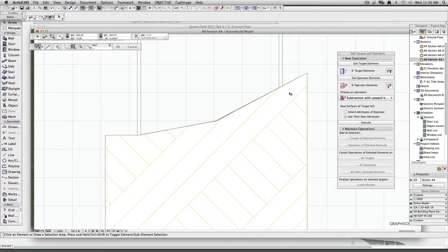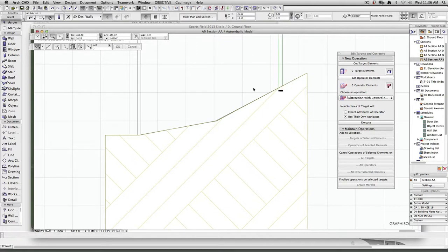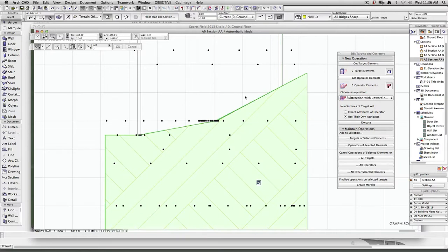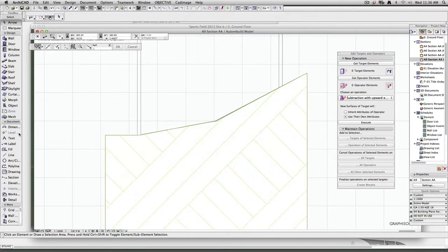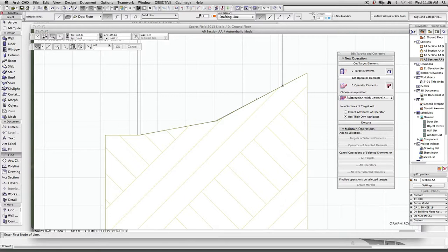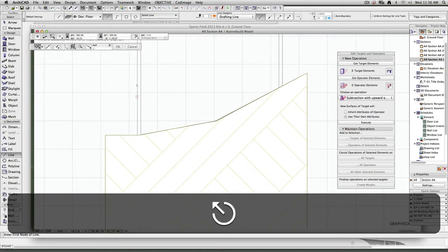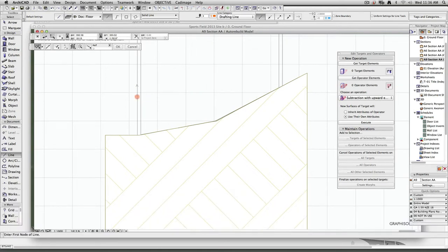So that means, as I said before, that's going up to 18.13. So let's say I make my stairs go up to 18. So 15, 16, 17, 18. So I've got 3 metres. And I've got a run from the top here to over here. It's about 10 metres. Cool. So that means that if I make my stairs 1 metre each and 0.3 high, I can fit my stairs quite nicely into this, and they'll start down the bottom and go up. That's actually going to be the base as well. Just remember that's from the bottom there to the top there, so my stairs might be a little bit higher.